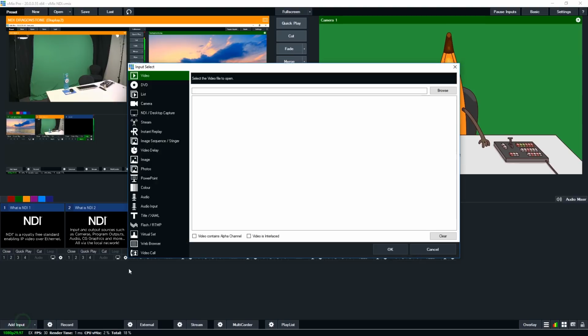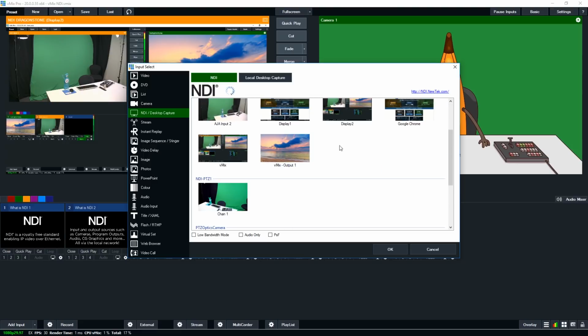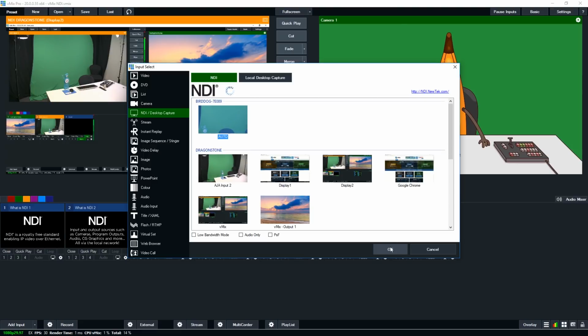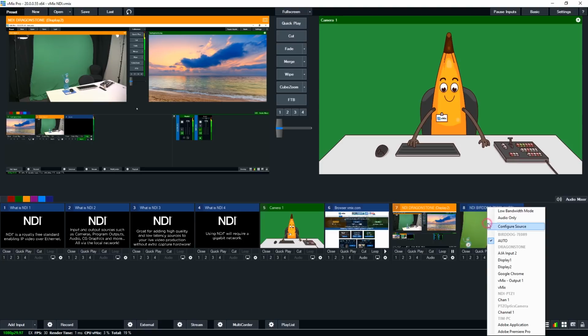Say I wanted to add another one, I just click Add Input, go to my NDI section, and I can select, let's say, this Bird Dog Studio. So now I've got two NDI devices in my production. Let's just say I don't want to add a new one, but I just want to change it. I can right-click and bring up the NDI menu, which allows me to select a different input.